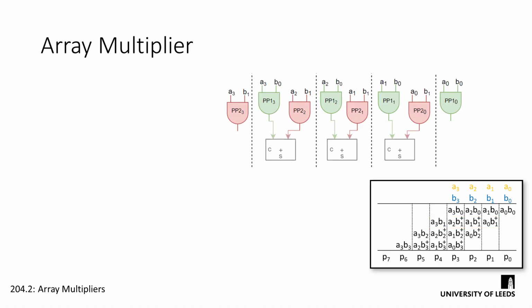We'll use 1-bit adders to add our partial products as we go along, so that the RTL diagram doesn't get too confusing. Again, we take the reference from our general model to see which bits of the partial products need to be added together. We then link the line of adders from carry out to carry in to carry any excess values into the next column. Our last column on the left doesn't have a bit of the previous partial product to be added to, so we can just add it to the carry out of the adder on the right.